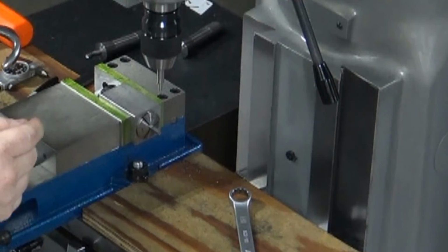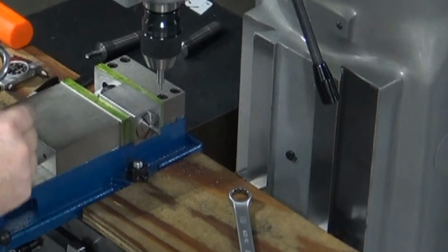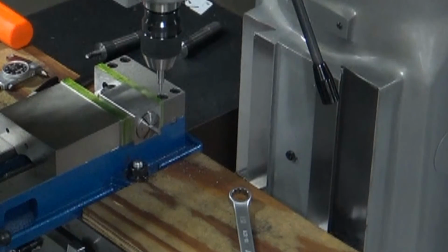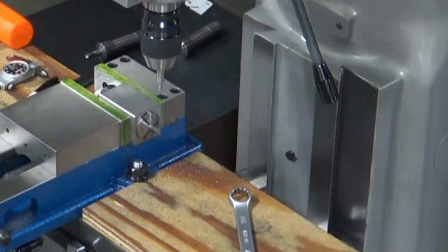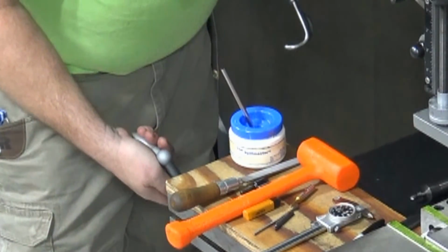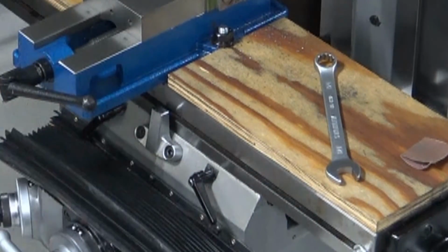So now if you look at your part drawing that you have printed out, we're calculating our X dimension right now. Again, my part's perfect at 930, right? 930 minus 813 is 117 thousandths. So I'm going to move 117 thousandths. I'm going to lock my table into position.